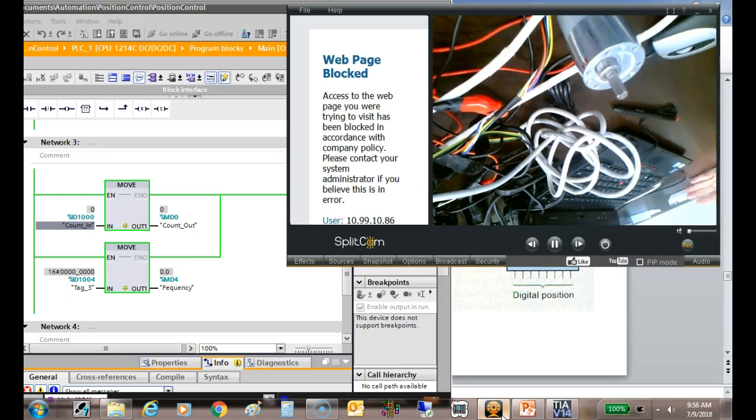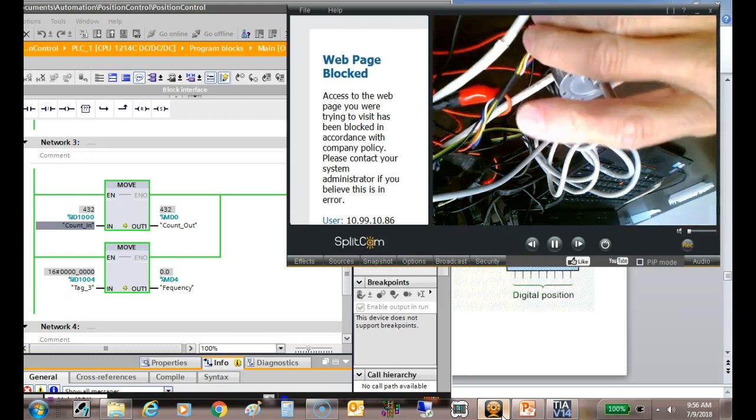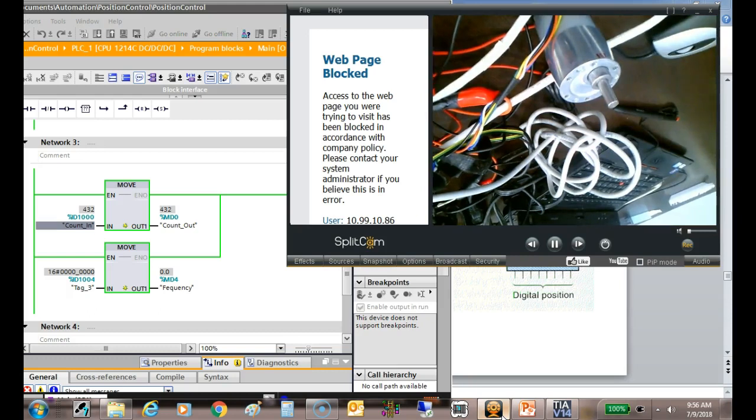So an absolute encoder gives you a position. An incremental encoder, you have to start from a reference point. So all the robots over there, we have what we call an origin point that we have to establish, and that's where it counts from, right? Does that make sense? That's why all the robots have batteries on them, because if you lose the origin, then we're what? We're lost, right? That would be like I come over here and spin this a little bit. What did I just do? I've lost my reference point, and now it makes no sense where we're at.